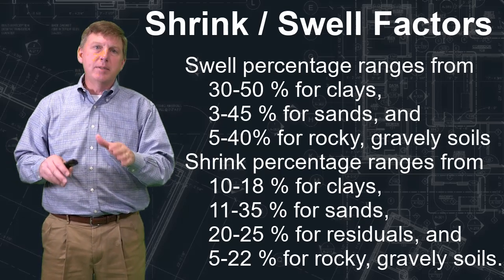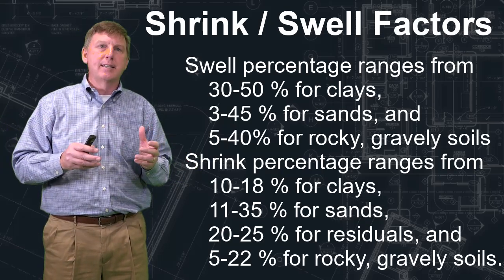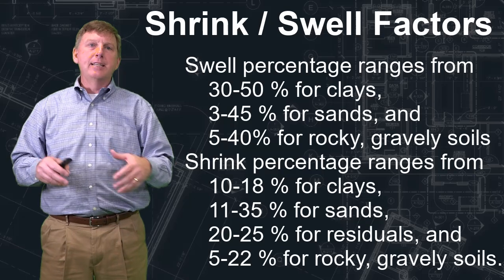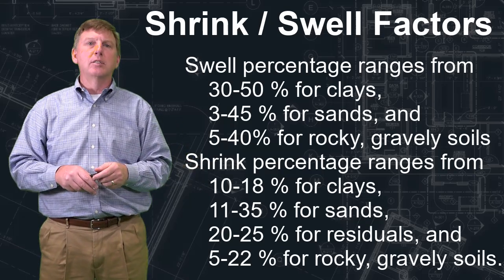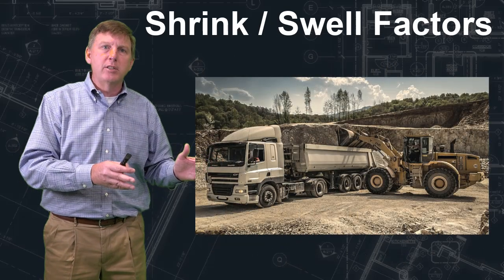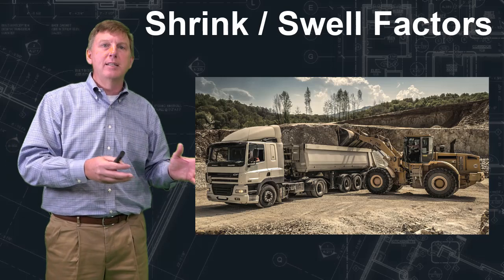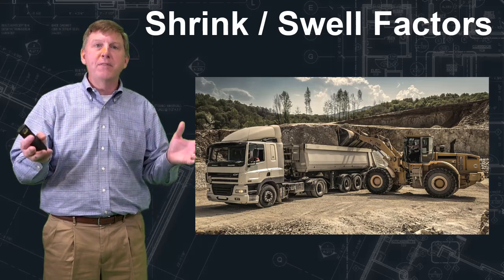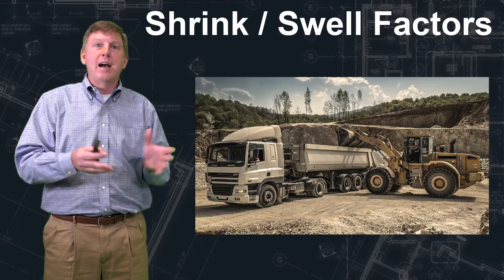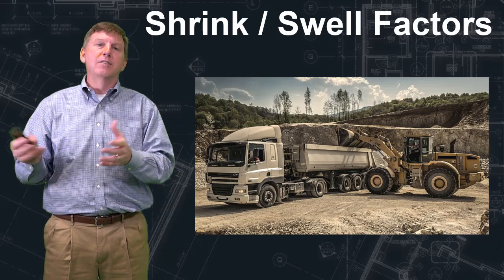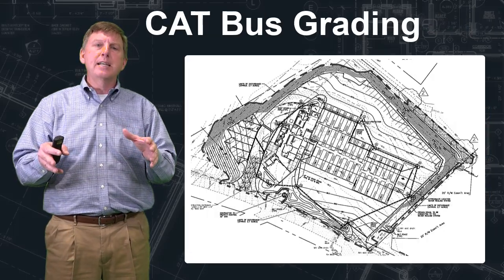This is extremely important when you're hauling soil away from the site or bringing soil into the site. Let's say you determine that you need to haul 20 yards away because you're cutting 20 yards. Well, that 20 yards that you cut will not fit into a 20-yard truck, because when you cut it, it will expand by up to 50% depending on the soil type. And therefore now you have 30 yards and it's not going to fit into a 20-yard truck. So there's a lot to consider when doing a grading estimate.